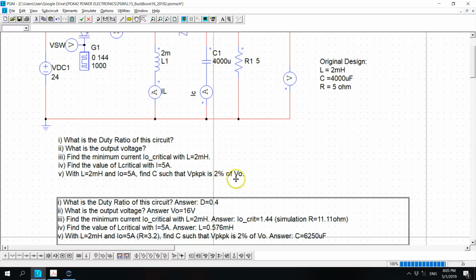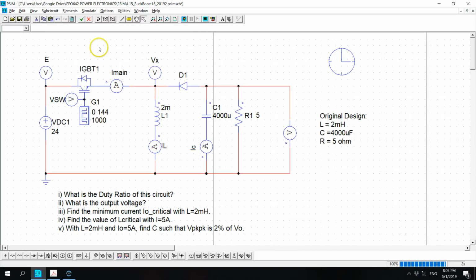And if you want to simulate that, of course you have to derive the R in the circuit. Therefore you can use V out, R equals to V divided by I to get the value of R, and then you plug into the simulation circuit, and then you run, and then you can find the current. Okay, can I do that? So now let's run it together first.